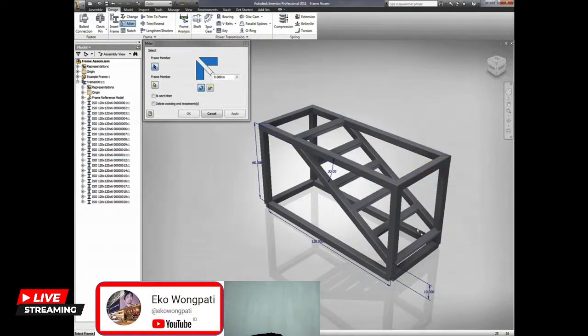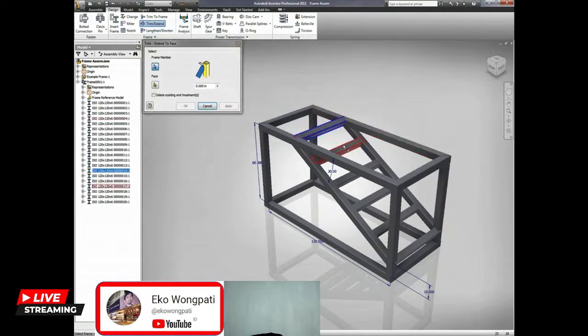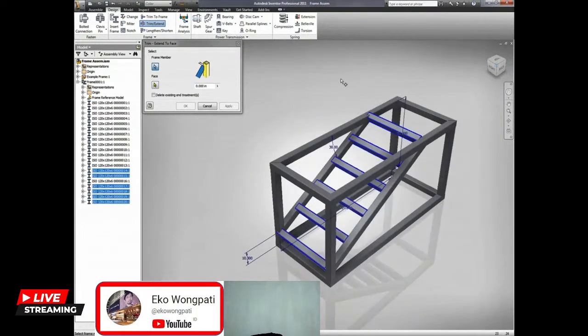After the different structural member components are completed, we can perfect the frame design by cutting and coping, mitering the different joints and components within the interface, and truly digital prototype the components before we start cutting steel. Now, the other things that we can do is we can actually go in here and start extending or trimming off specific componentry within the design so that we can perfect the design and also analyze the design downstream. So what we have digitally is what we're going to have in real life.